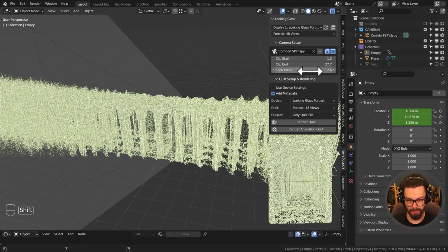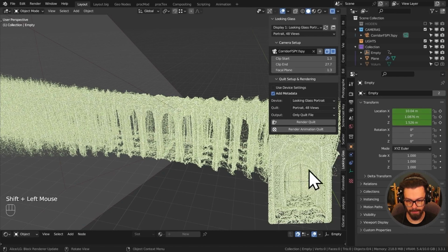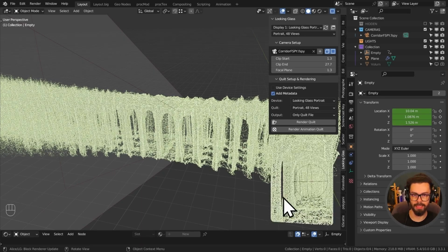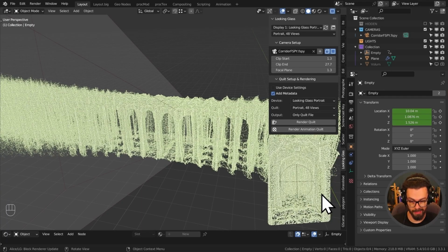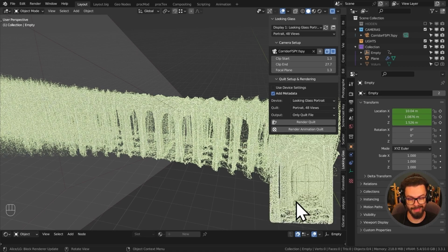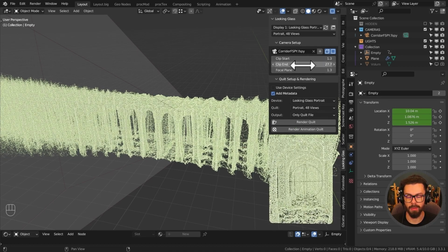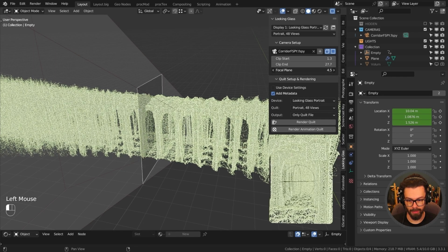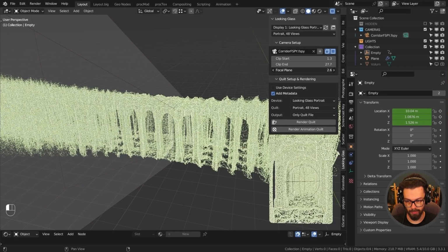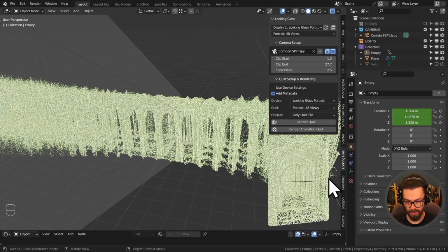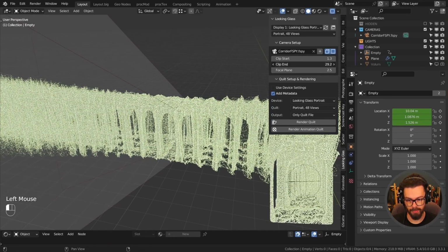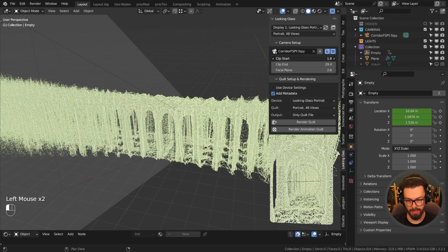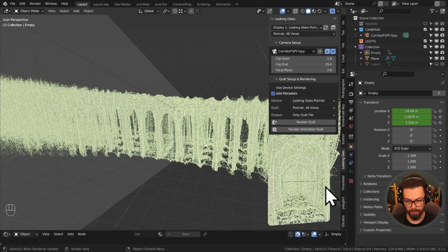Now, if you pull the focal plane back towards the camera, then it's more like the camera is looking from side to side. This works all right for blocks, but it's actually quite bad for the looking glass displays. So if you want this to be a bit more multifunctional, then I would recommend having your focal plane just a little bit further away, and maybe change your clip start just to get rid of some more of those nearby things which actually swing into the view. So that's looking pretty good for me.